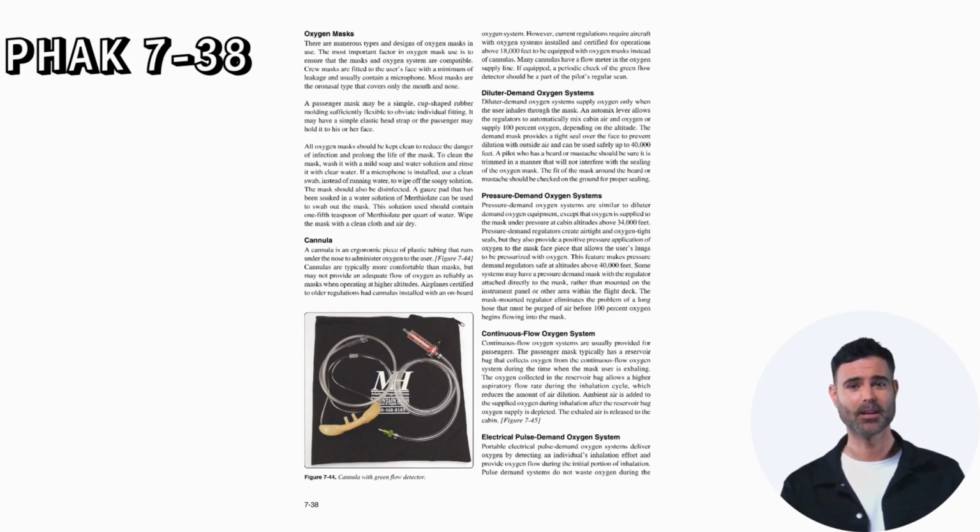Cannula. A cannula is an ergonomic piece of plastic tubing that runs under the nose to administer oxygen to the user. Cannulas are typically more comfortable than masks, but may not provide an adequate flow of oxygen as reliably as masks when operating at higher altitudes. Airplanes certified to older regulations had cannulas installed with an onboard oxygen system.